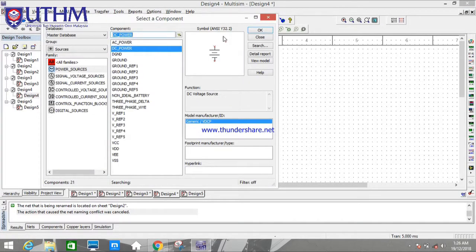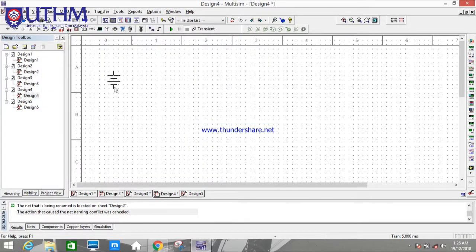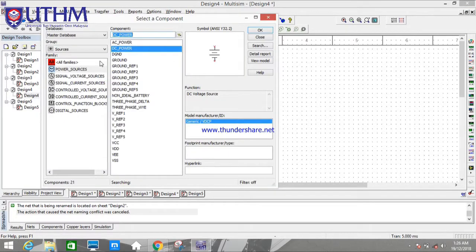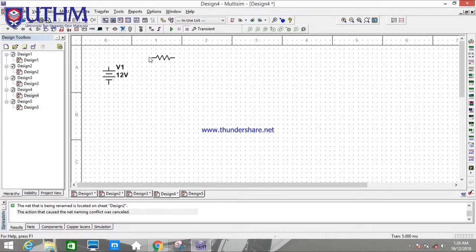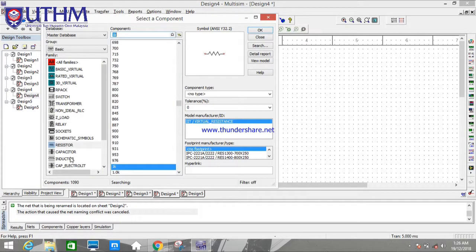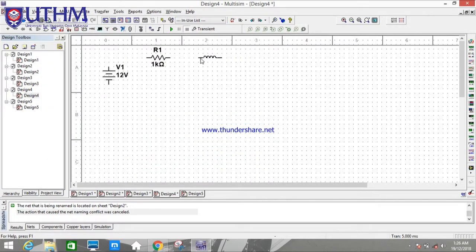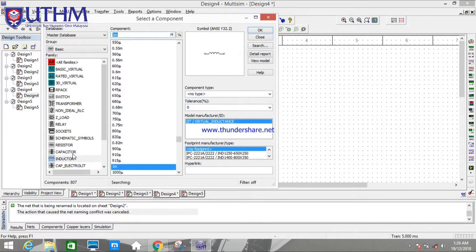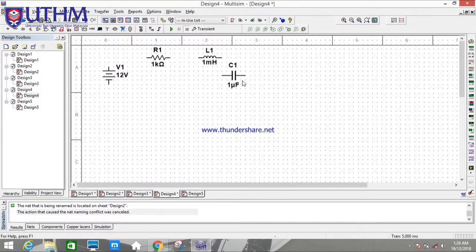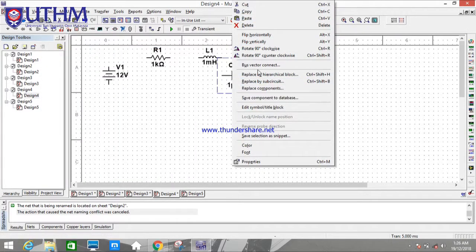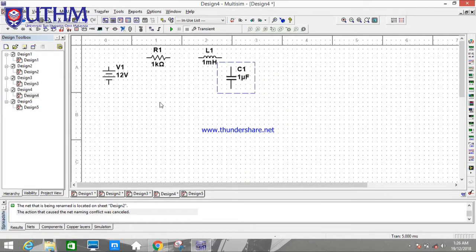Case 1 will be identifying the underdamping, critical damping, and overdamping. For that, we have to build three different types of circuit. As we mentioned in the objective, our circuit will be an RLC series circuit. So the RLC series circuit will use a DC power source, a resistor, an inductor, and a capacitor with a ground.